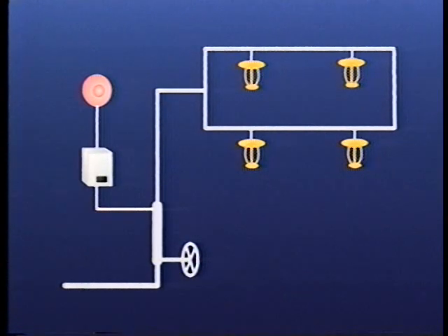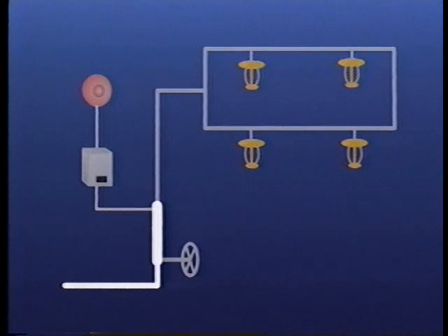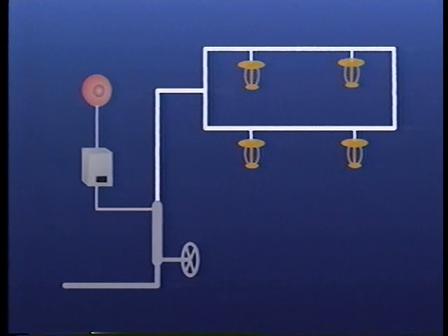According to the National Fire Protection Association and NFPA Standard 13, a fire sprinkler system is defined as an integrated system of underground and overhead piping designed in accordance with fire protection engineering standards. The installation includes one or more automatic water supplies. The portion of the sprinkler system above ground is a network of specially sized or hydraulically designed piping. It is installed in a building structure or area and is generally overhead.